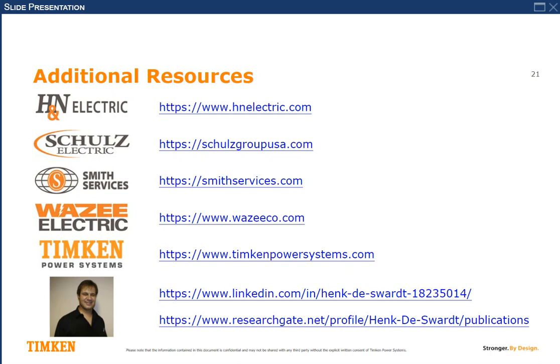Sure, absolutely. Most machines out there are monitored continuously by temperature and vibration. As I mentioned earlier, have a look at your temperature monitoring. That could be in your SCADA system. Monitor it over time. If there's a significant change and there's no load change, you need to investigate. And that is done continuously, temperature and vibration.